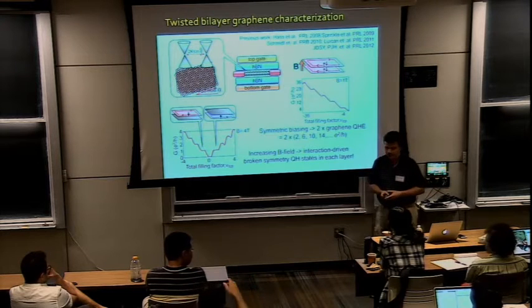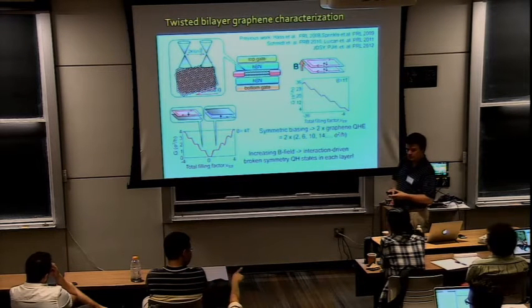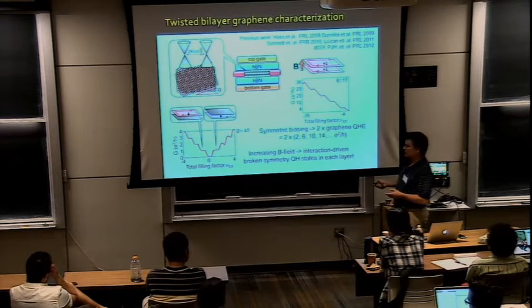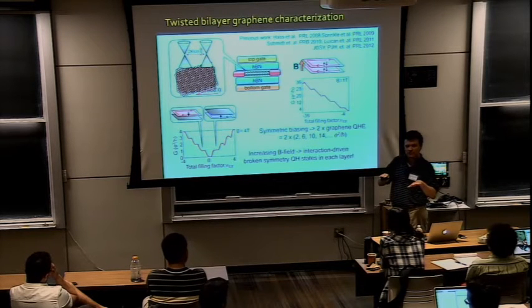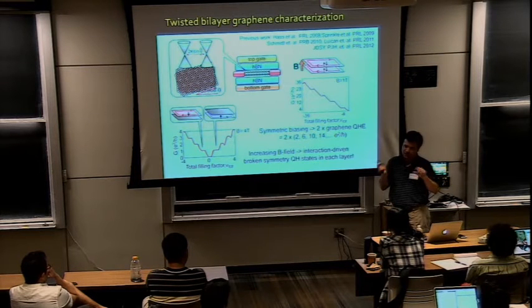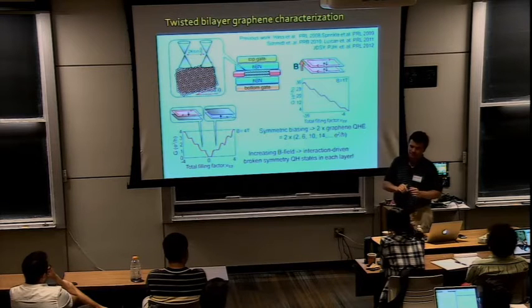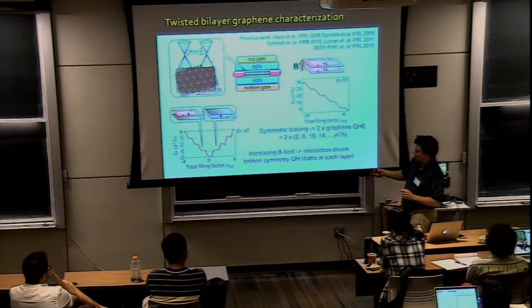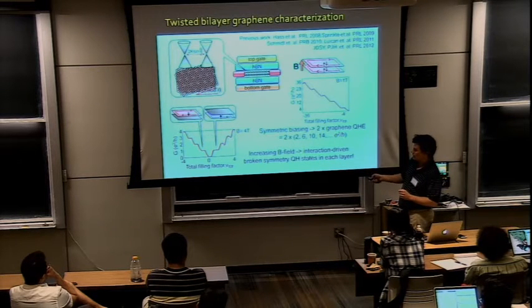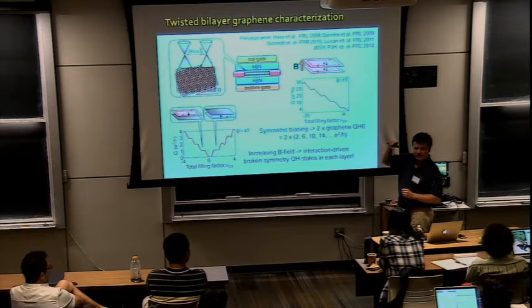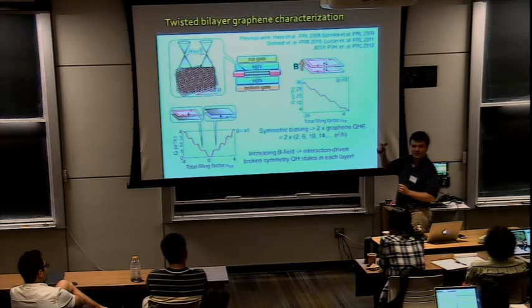Is there any reason that it only happens for positive? In addition, because these are two-terminal measurements, you can have a p-n junction with the metal contacts, which sometimes leads to an asymmetry that is more pronounced in one polarity than in the other. Also, one layer, depending on the type of electric field, I will comment again on this later on, because one layer is p-type and the other layer is n-type. No matter what you do, you're always going to have a p-n junction with your metal.